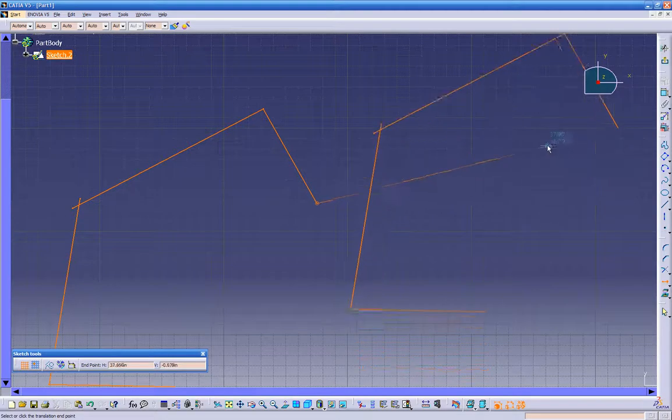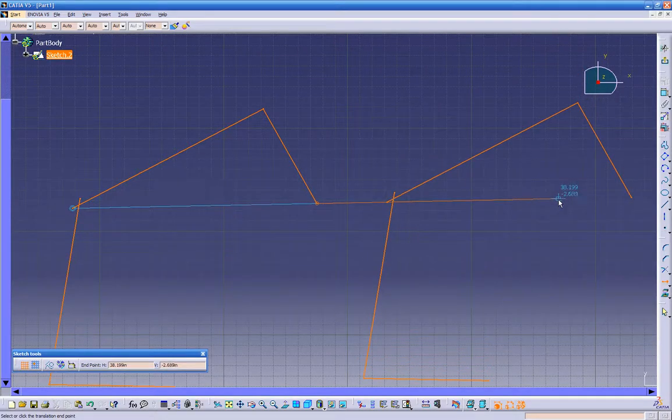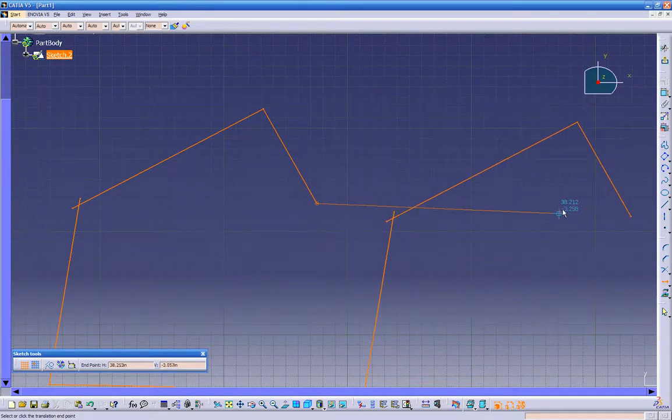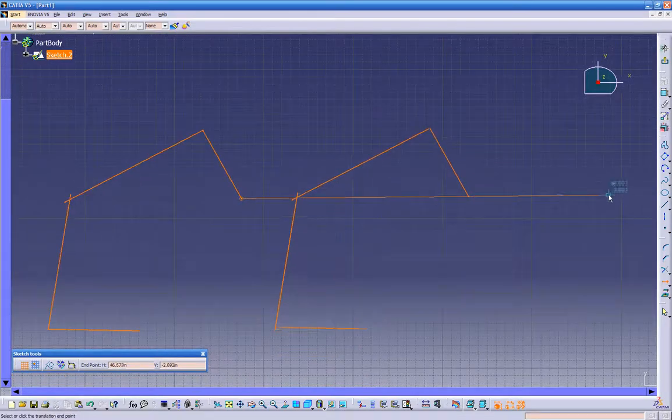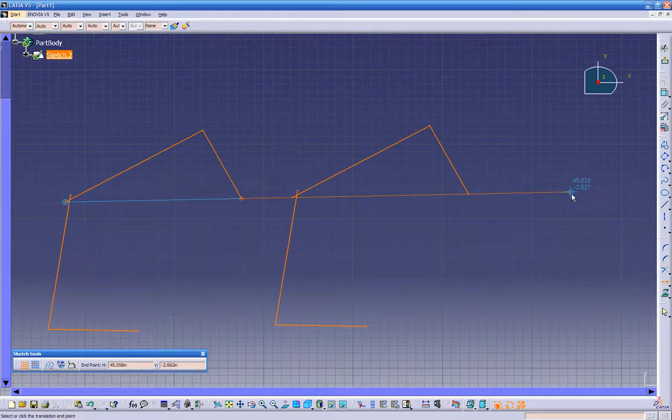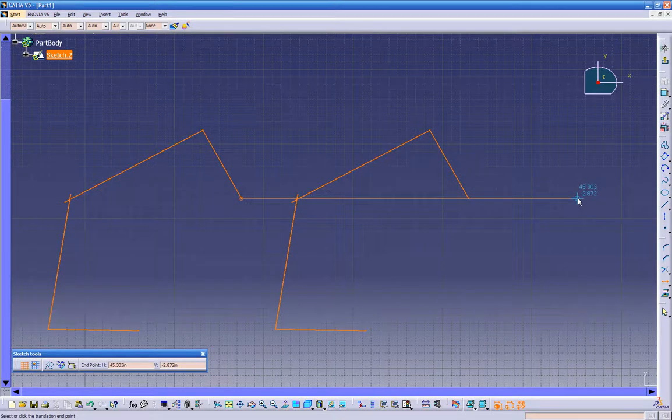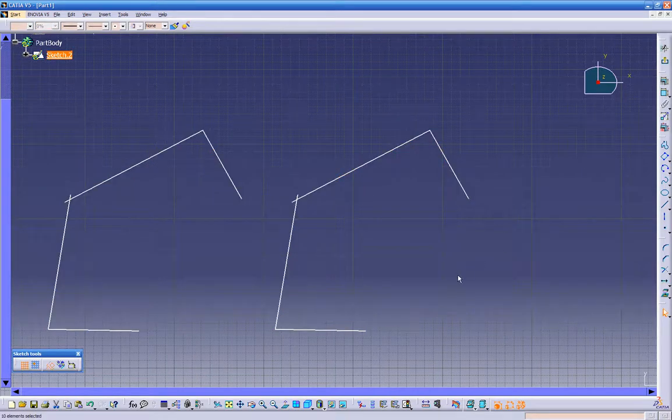While you move the part up and down, once you bring on the vertical dimension, it automatically is going to snap 10 inches apart. So right now, if you want to give it a double check, we can click on the constraint. We can click on this point with this point, and there's our 10 inches.